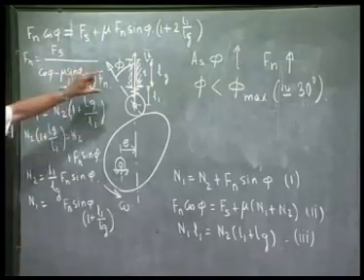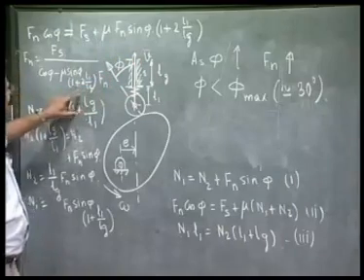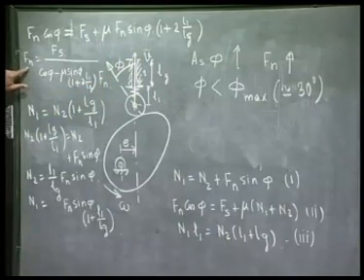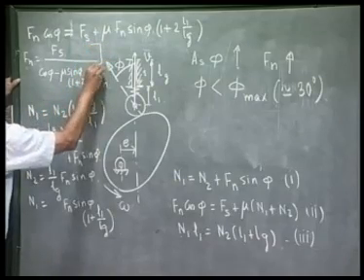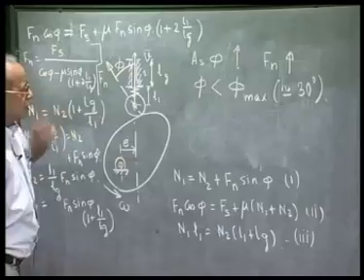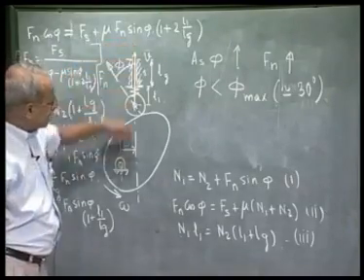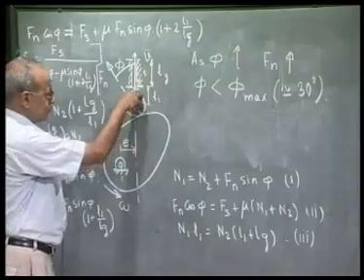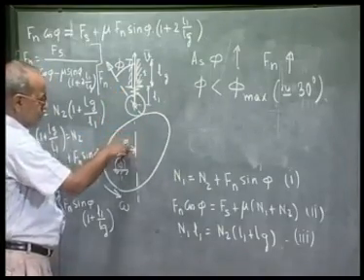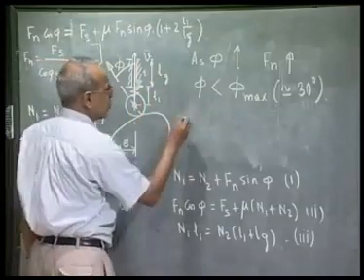We also see that this Lg appears in this expression, so a proper guide length is necessary to control the value of Fn. The length of the guide is important. Of course, while follower is coming down, it is the spring force which pushes the roller down and keep in contact with the cam, and the pressure angle is not important.